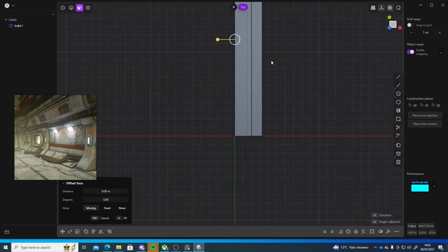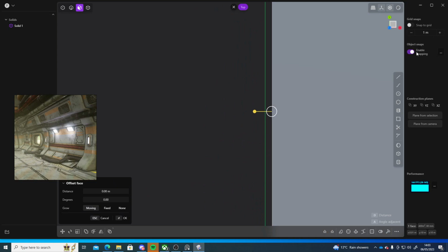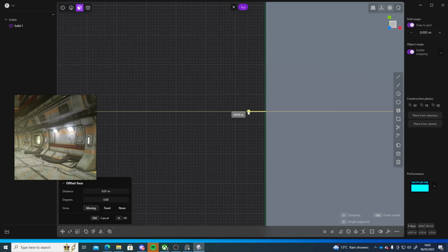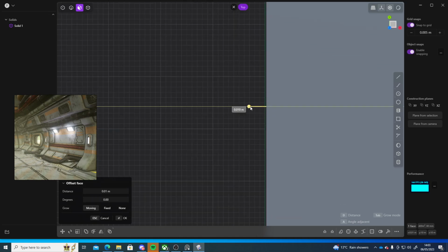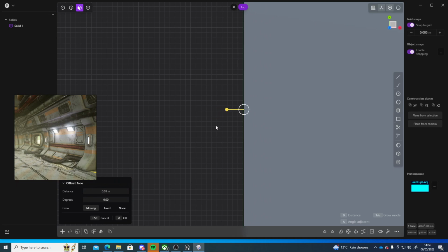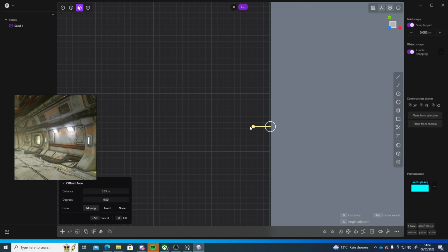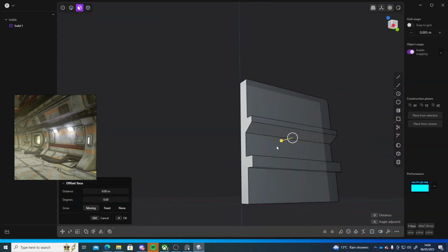It's really important that I can keep the outline of the shape exactly that size so that it snaps perfectly in Unreal. So I'm going to enable snapping, or snap to grid on. Let me see. Let me just drop that, snap to grid. Because it's already offset, let me see if I set that to 0, what does that say? Yeah, it's a bit annoying that it's not going to be perfect. Not too bad on the width here, but on the length I definitely need it to be perfect. So I'll just switch that off and manually move it until there. I'm going to have to figure out a better way of doing that for future cases if I want to create exact measurements. Well, there probably is a way.